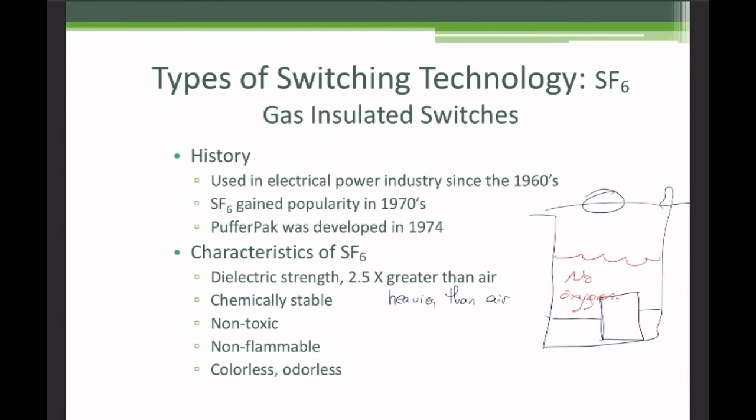The other problem with SF6 is it is a very powerful greenhouse gas. It's among the worst that we've produced, and it's one of the few of its class that's still manufactured. And it's manufactured primarily because of its very niche use. People are still buying SF6 switchgear. It's still cost effective, and for a lot of applications, it's still a very reasonable way to go.